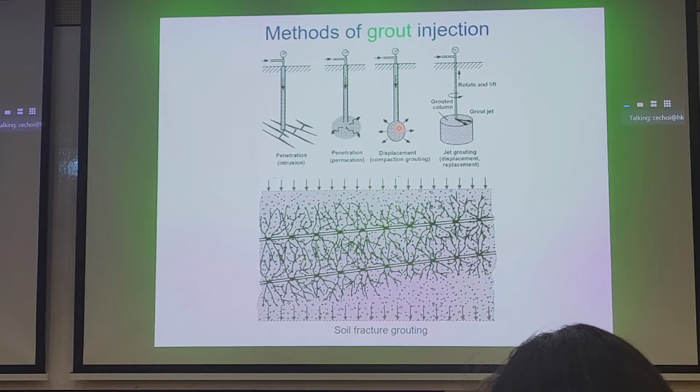On the far right, we have something called jet grouting. If you recall from the earlier slides of this lecture, we mentioned that this is perhaps a hybrid approach between grouting and deep cement mixing. This approach perhaps is the most uniform in terms of the stabilized soil quality. What we mean by that is, in jet grouting, there are three approaches.